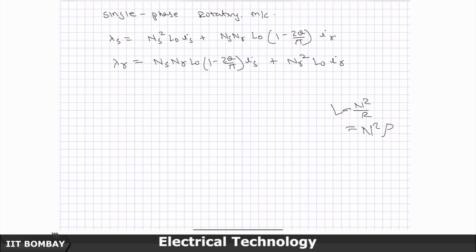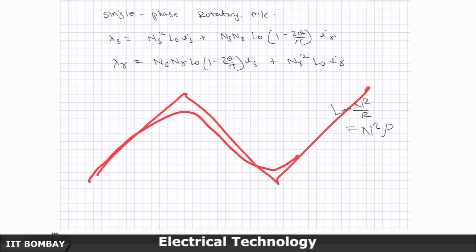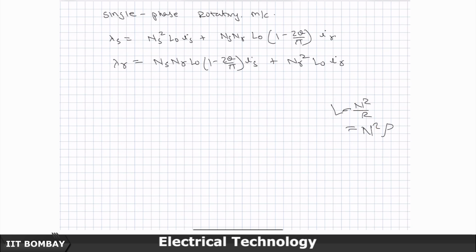And so, the point which I am trying to make out is, this is something we know, but this is with concentrated windings. When you look at this kind of triangular waveform, again when you do a Fourier analysis, you will get a fundamental component and harmonic components. Now, harmonic components of the fluxes will create harmonic voltages, which we do not want to have.